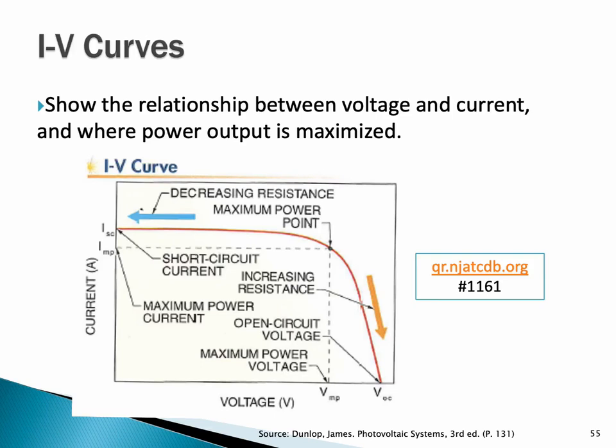Once I make that module or array do some work, I connect it to a load, then that voltage sinks down into VMP, or voltage at max power. If I draw a line up from VMP to the curve and IMP over to the curve, this is called the maximum power point, at this point right here. That is the sweet spot, or maximum amount of power my module will put out under ideal conditions.